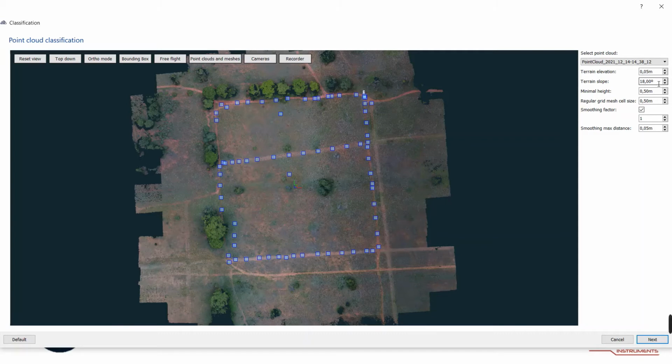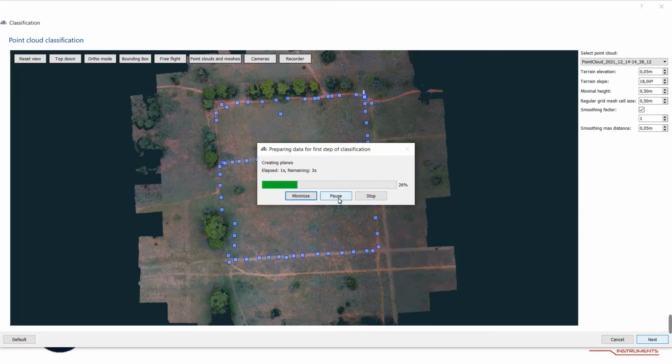assume that it's ground. When you're doing volumetric calculations, this is definitely the optimal setting, but for places such as this, you can actually decrease your degrees to give you a smoother surface and actually a more relevant surface to what the ground really is like. But for what we want to do today, we're just going to keep it as the custom surface or as the default settings and continue on that.